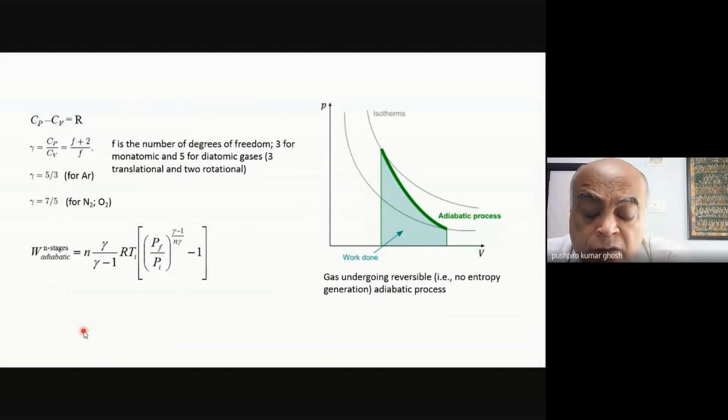If you look at it from a chemical engineer's perspective, what is very important is that when you are doing this kind of liquefaction of the gas, and then of course it will subsequently be fractionally distilled to get the nitrogen and the oxygen in pure form, the energy that you really put in is what energy? What energy did you use in the system? For compression, right? We had to first compress the gas, and then only you can expand it, right?